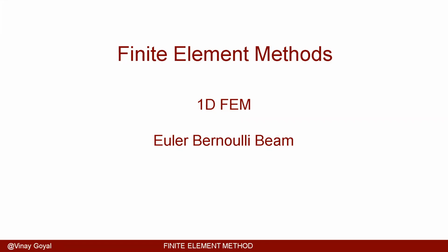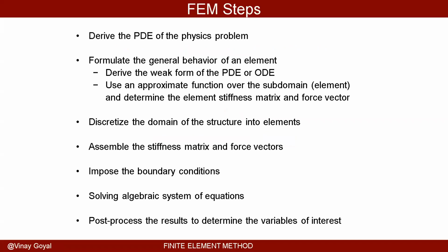Today we'll be discussing the 1D finite element formulation for the Euler-Bernoulli beam, and I'll be discussing how to formulate the 1D Euler-Bernoulli beam. The ideas in finite element analysis are to really approximate the solution to a partial differential equation that governs the behavior of a structure over a very complicated domain.